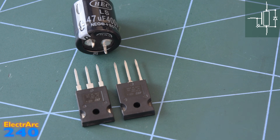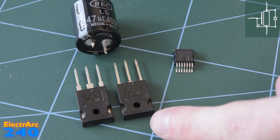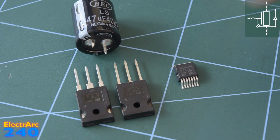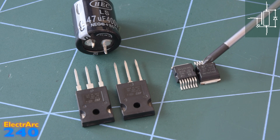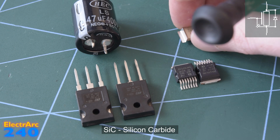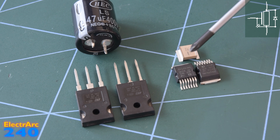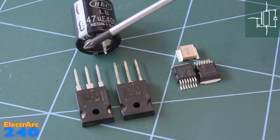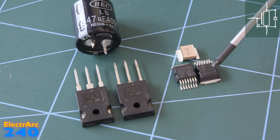This MOSFET is a 7-pin TO263 package. The silicon inside is pretty much the same as these MOSFETs, but the package is clearly much smaller, and even more so once you put it next to its friend. This is quite a modern package, and it's what a lot of the best current MOSFETs, especially silicon carbide, come in. If we combine that with a fancy modern capacitor, this is called a Ceralink, then you can see how much smaller the loop inductance is on something using modern surface mount components than old-fashioned through-hole. So even though it may make cooling more challenging, you might find there's a lot less cooling to do, because the parasitics are so low that we can switch a lot faster and have less switching loss.